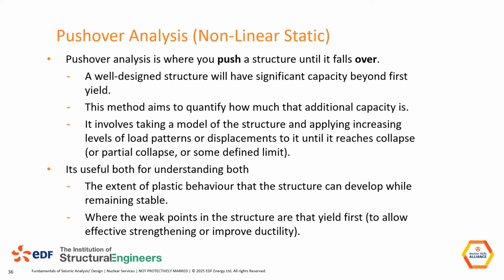So once you get the onset of yield, in an elastic analysis, you stop there. This is telling you how much further you can go. And typically, for a well-designed structure with a lot of ductility, you can go way beyond the initial onset of yield. It also tells you how the structure fails, which is also useful to know. If you want to strengthen something, you want to know where to focus any strengthening measures or where to do some redesign. It tells you that as well. But this is a pushover analysis, and we're still static here. We're still talking about loads which do not vary with time.